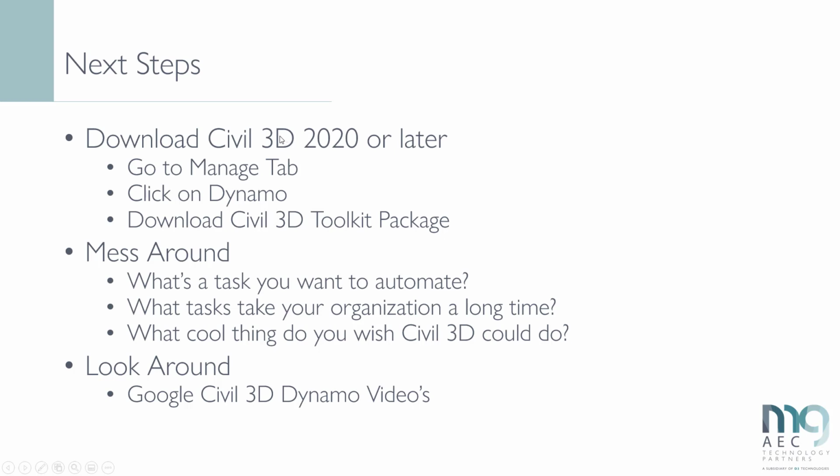And anyone who's on 18 still, I know a lot of people are on 18. 2020 and 18 share the same base version, so you don't have any data loss or any conversion of versions when you go from 18 to 2020 or 2020 to 18. So they work seamlessly. So does 2021. There hasn't been a version change between 18 and 21. So don't worry about collaborating with other people in your company. It's seamless going between 18 and 2020.